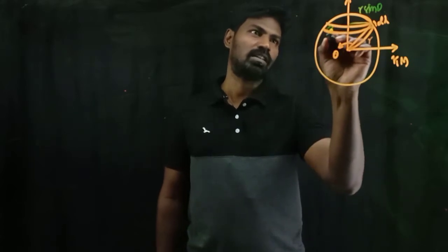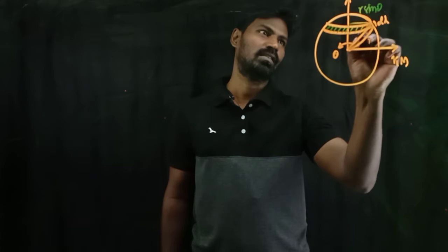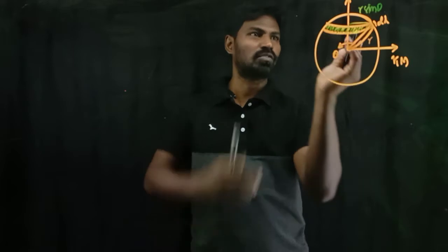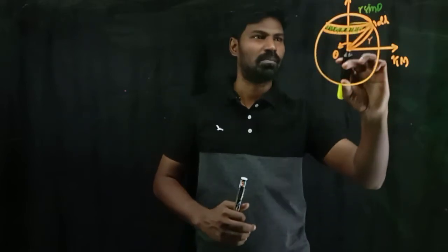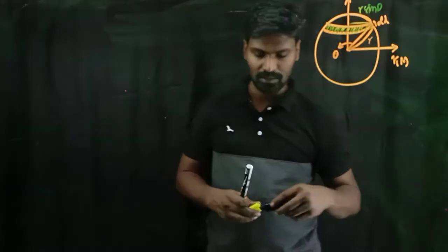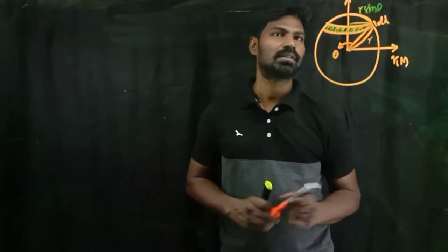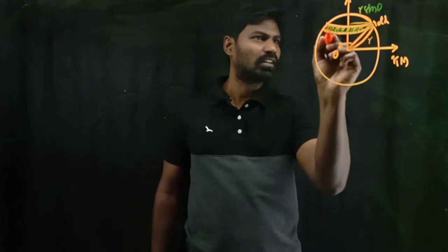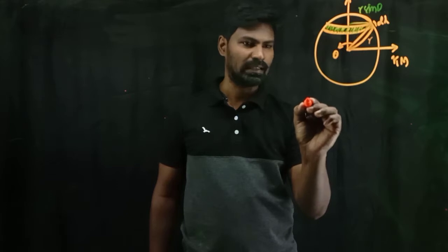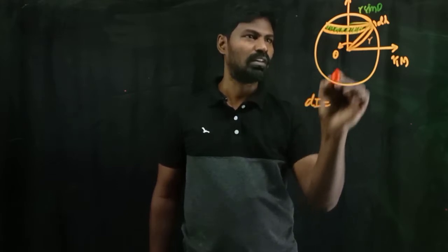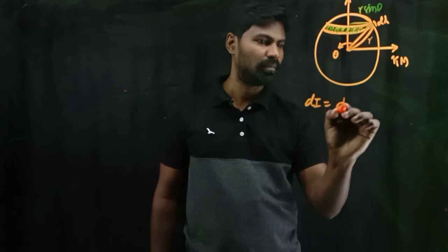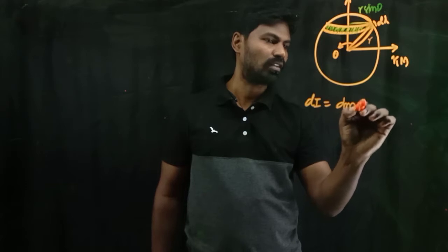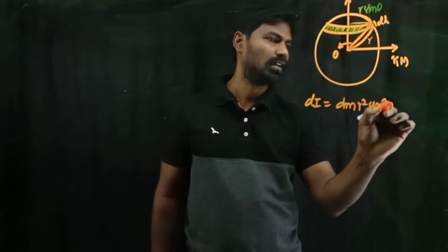Now, the mass element that I am considering is this one. If you divide this sphere into small annular strips like this, one by one, and keep on arranging them, we will get the complete shape of the spherical shell. So first, I want to define the moment of inertia for this strip. That is dI. dI is equal to, if you take this mass as dm, into the radius of this circular strip, r sin theta, so r squared sin squared theta.